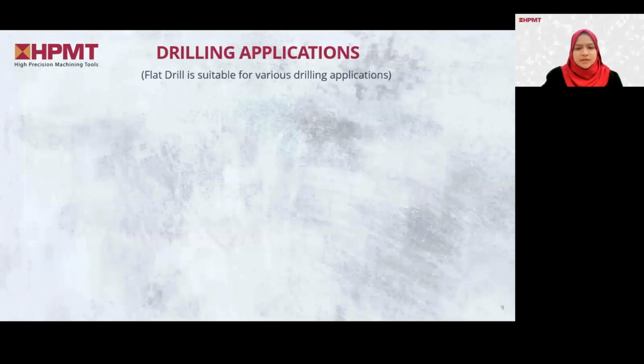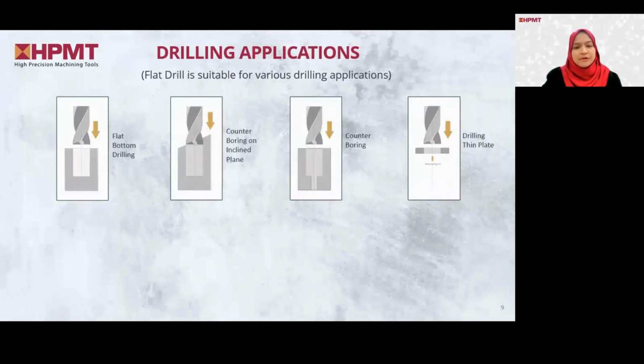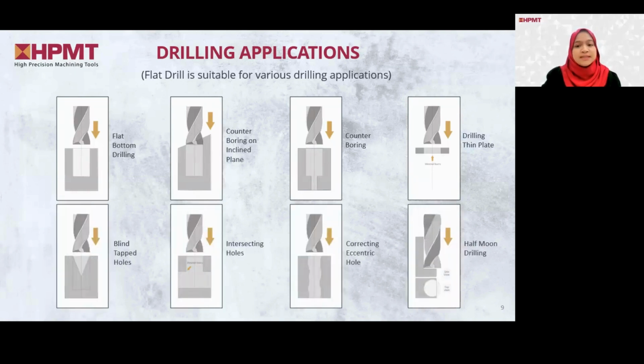All right. So for the next one, we will look into drilling applications for flat drills. It is versatile and suitable for a wide range of drilling tasks, including flat bottom drilling, which is ideal for creating precise flat bottom holes, counter boring on inclined plane, which is perfect for angled surfaces that require accurate counter boring, blind tap holes, which is great for drilling holes that don't go all the way through the materials, correcting eccentric holes, which is useful for correcting misaligned holes.